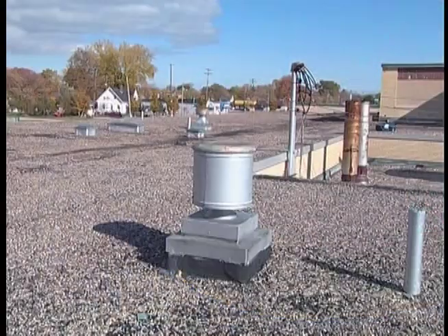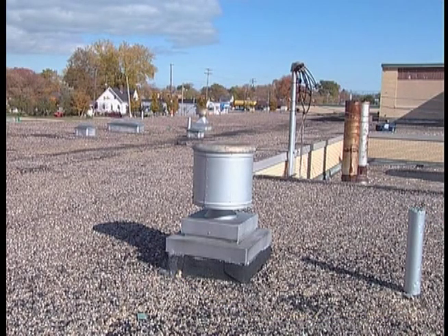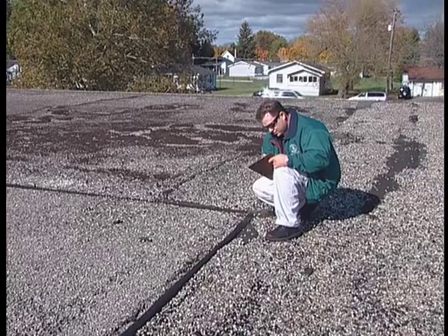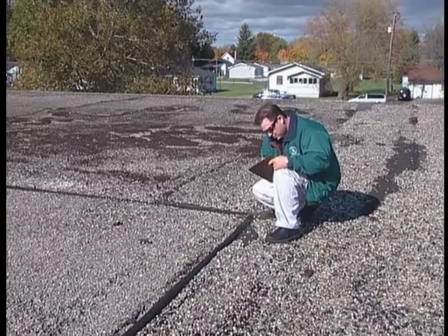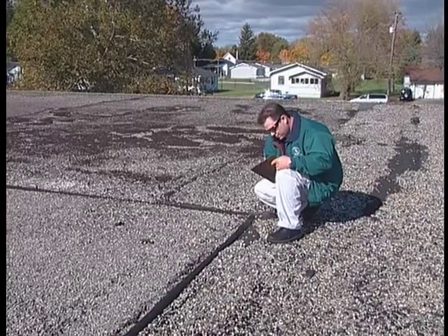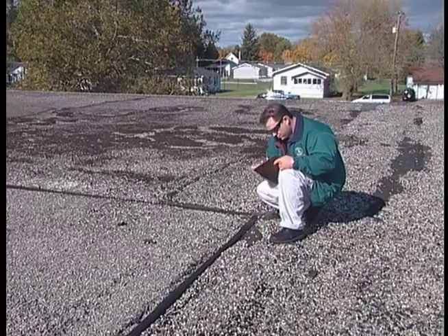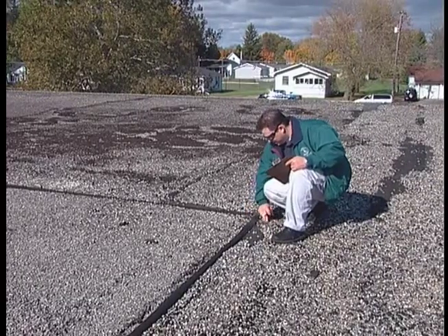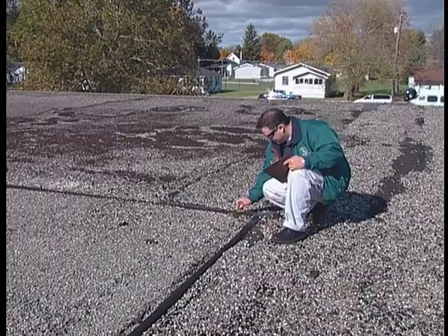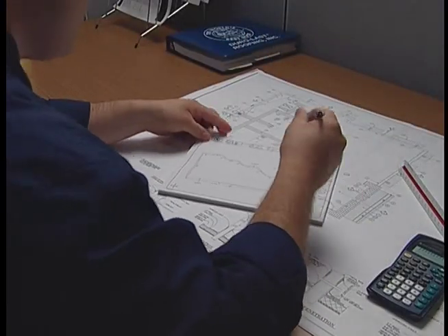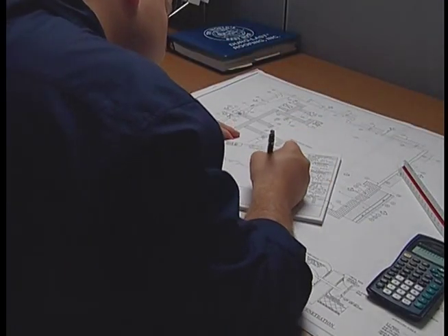The first consideration for planning a tie-in is to determine the type of existing roof and which tie-in method will be best. During planning, you will always need to calculate the amount of materials needed to complete a roof tie-in. You also need to determine whether the location is at an expansion joint, which is a good place to tie in to an existing roof system. Note that tie-ins must always be terminated to the substrate. Like all other measurements and planning, tie-ins affect the estimate.